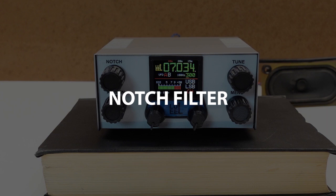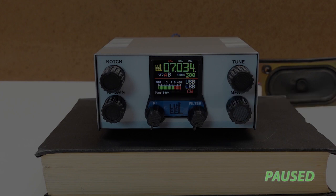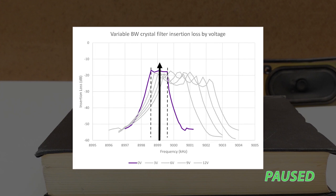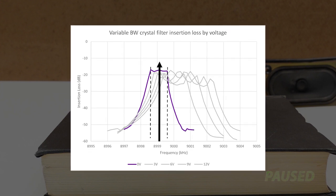In episode 5, I went into detail about the notch filter. Now let's hear it in action. What I'm going to demonstrate here is one of the most common scenarios where you'd use it. It's when you've got 2 or more CW signals that are close enough in frequency to get through your IF filter. Remember that my filter here is a kilohertz wide, which is pretty large for CW copy.